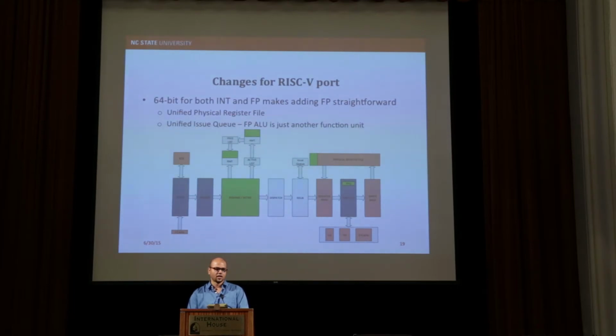This simply means that everything is treated as the same type of instruction, basically, and the pipeline does not need to know where the instruction has to go, except for the rename stage, which had to be modified to handle 32 additional logical registers. Since we have 64 logical registers now, there's also the additional committed state. For that, we need to add some space in the physical register file as well.